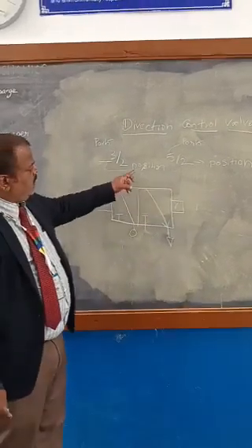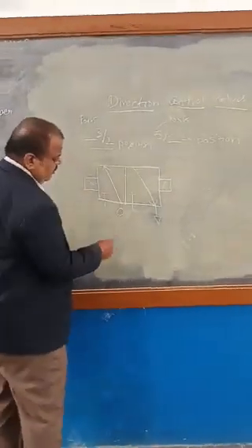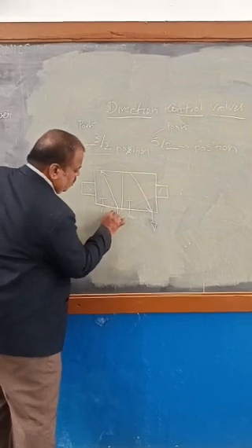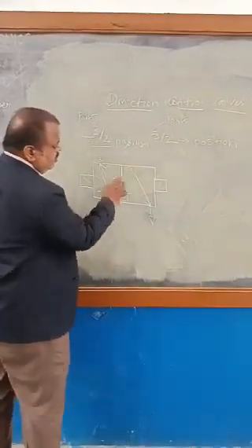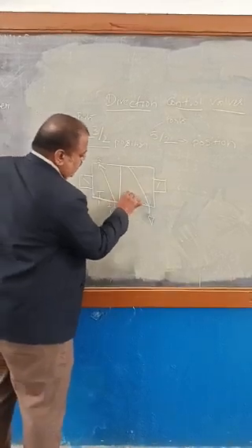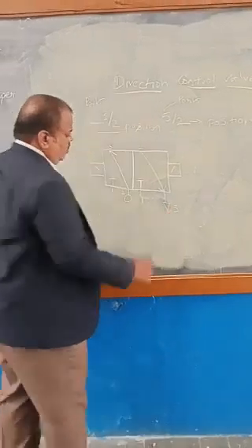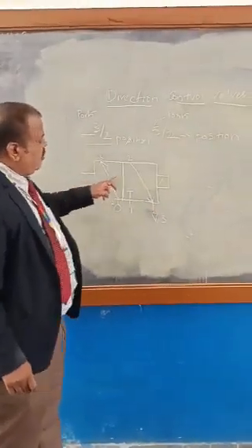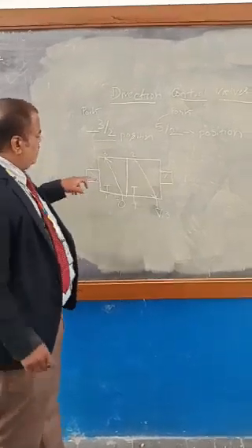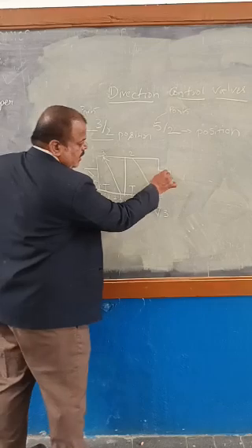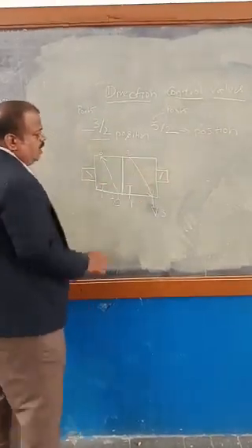And now you can see the 3x2 direction control valve. Here is the first port 1, 2 and 3, and this separates the direction control valve, so it is 2 position. So 3 ports, 2 position, and it is operated by a solenoid, which is at the extreme end and refers to how it is operated. So this symbol represents the type of the valve. So this is a solenoid operated 3x2 direction control valve.